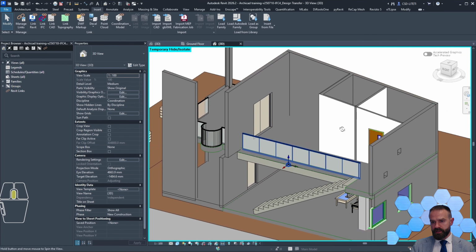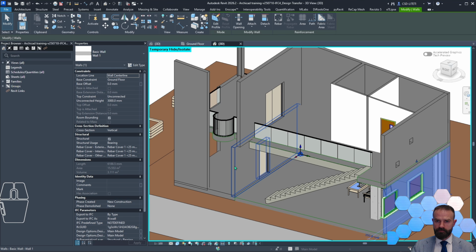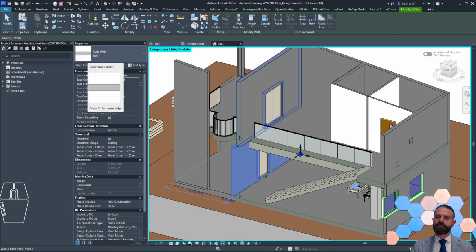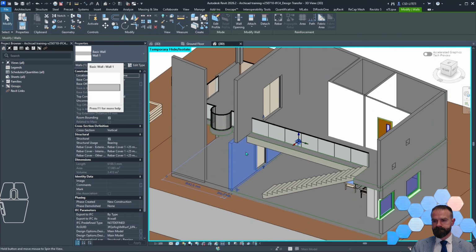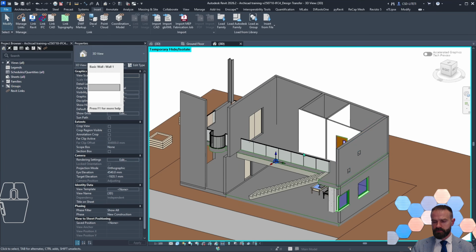Let's summarize. So, bearing floors and typical walls are converted to Revit system families, and you can assign Revit walls, and it can save you a lot of time compared to the typical technique of remodeling the structure part of the model using a reference architecture model. So using this technique you practically get all the geometry, walls and floors.